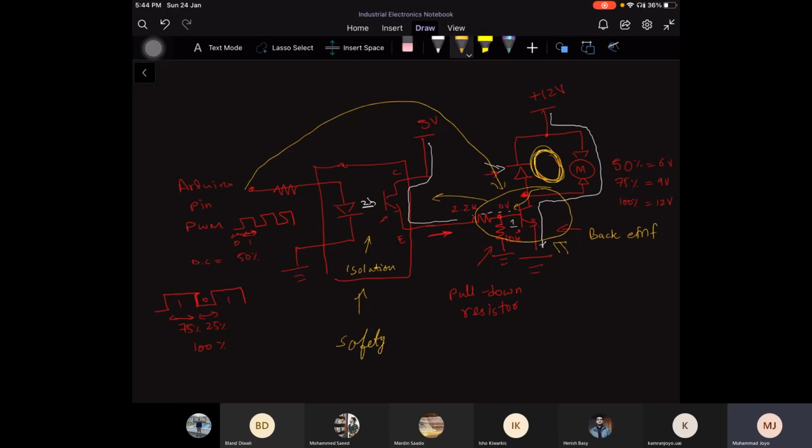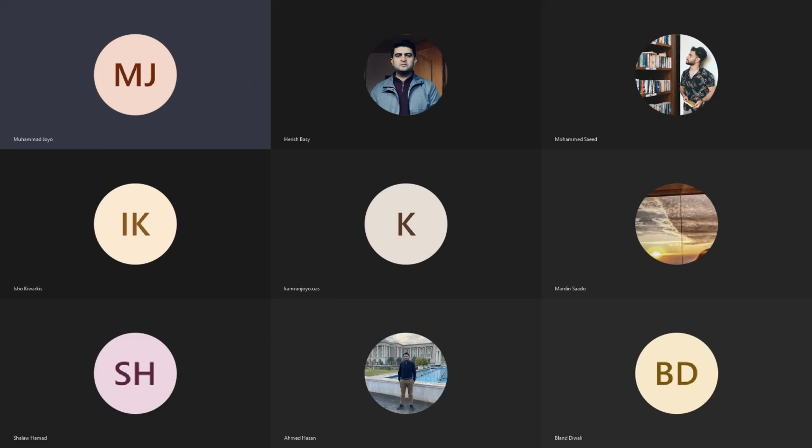It is basically a coil. You provide a signal to the coil, it induces EMF. It also sends the back EMF to the circuit. So there is a diode inside it. Usually it is there, but in most cases it is not. So you will have to attach the diode in a reverse bias way.